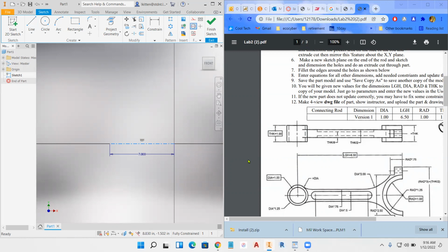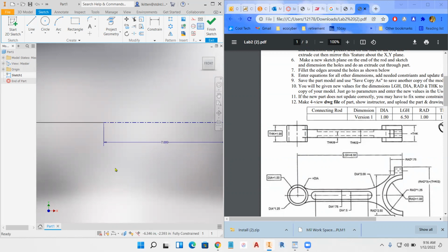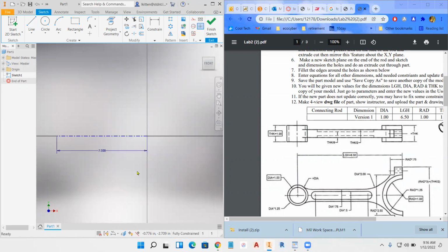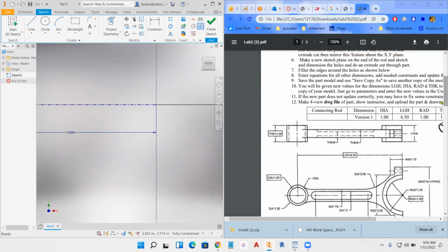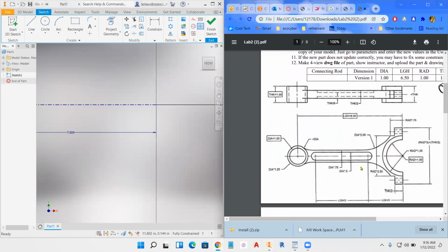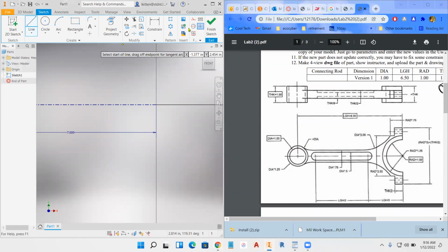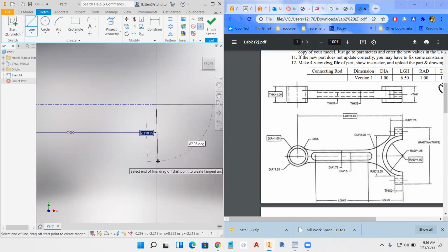Okay, now I think it'll actually do those dimensions across the center line if we're careful, hopefully. If not, we'll just put the regular old dimensions in and do them later, but it's a lot harder to do that. All right, so back to the beginning, pick line, turn the center line off if it's on, which mine's not on. We switched it after the fact, but if you did actually have it on, turn it off. And let's try to draw that line down here at the bottom again. And it's still not.